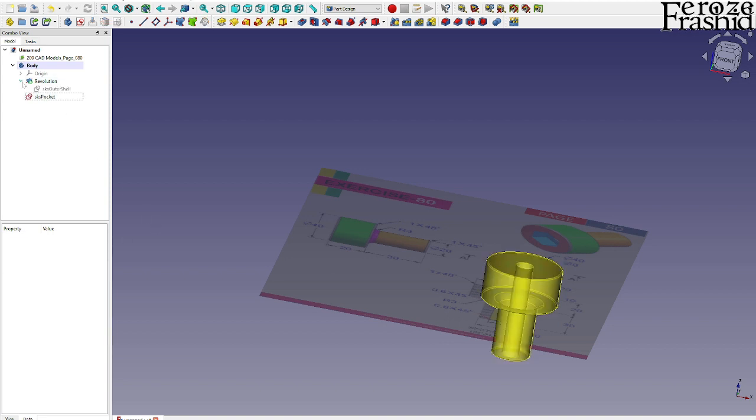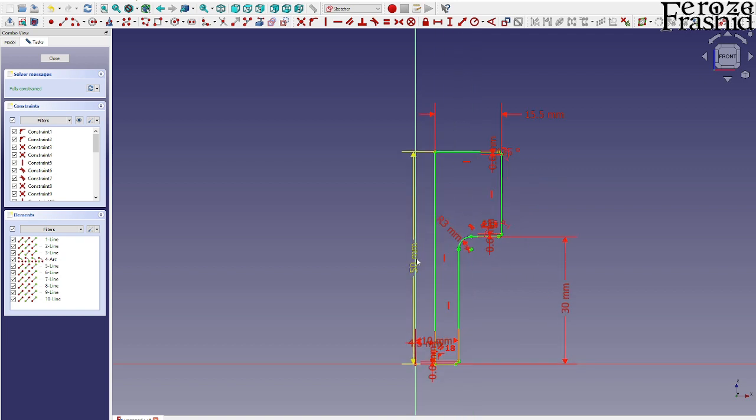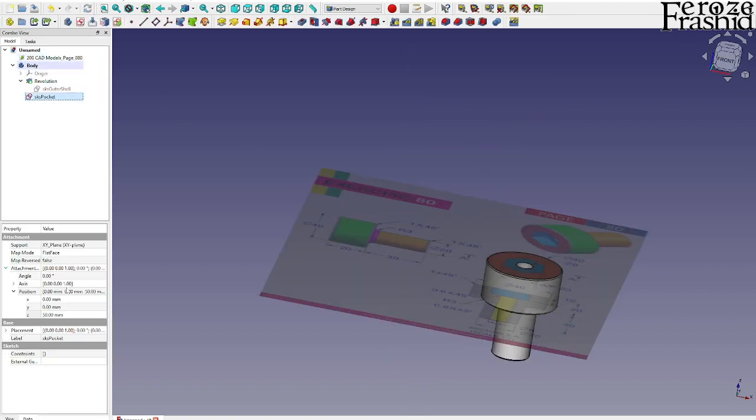And let's go back to that sketch and have this 50. So let's go ahead and name it as bolt height. Okay, so we have the name in there, right? We will use that in here.